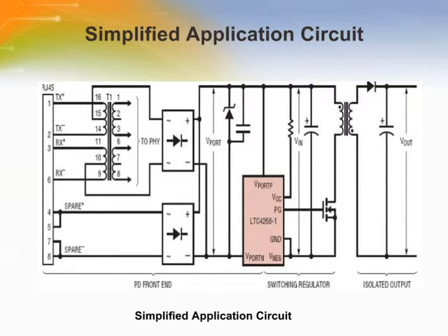The powered devices must be able to handle power received in either polarity. For this reason, it is common to install diode bridges between the RJ45 connector and the LTC4268-1. For the signature, classification and the undervoltage lockout thresholds, the LTC4268-1 extends 2 diode drops below the IEEE 802.3af specifications.